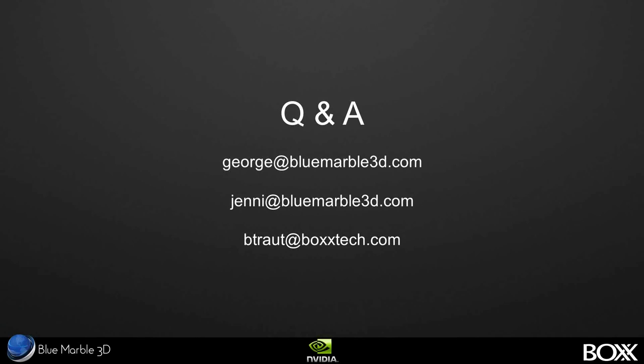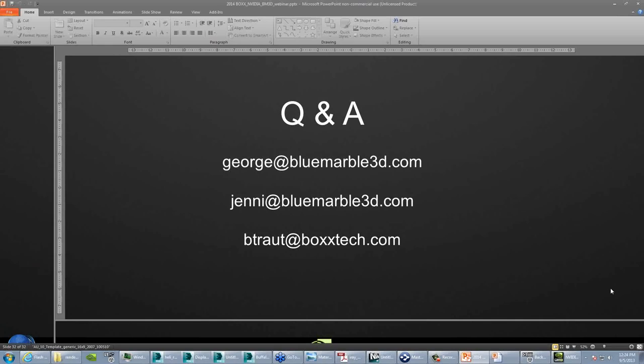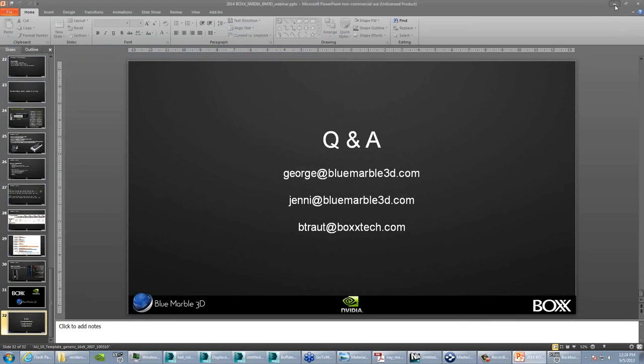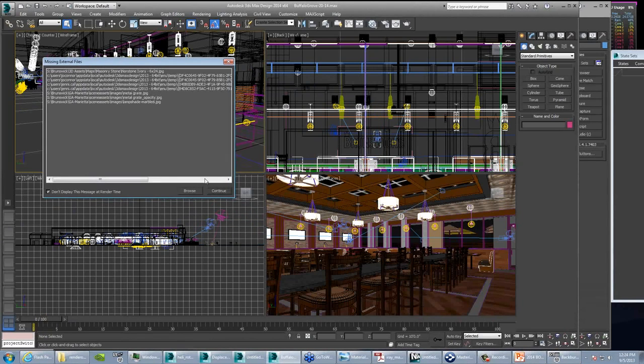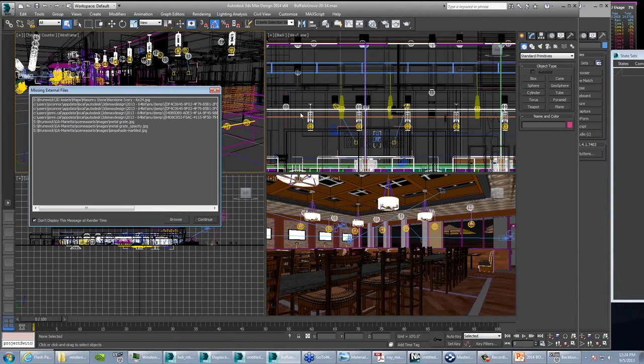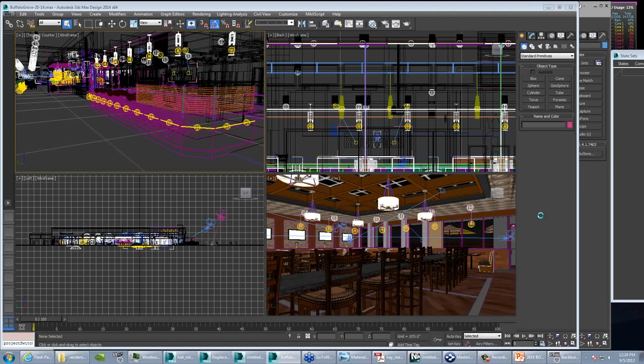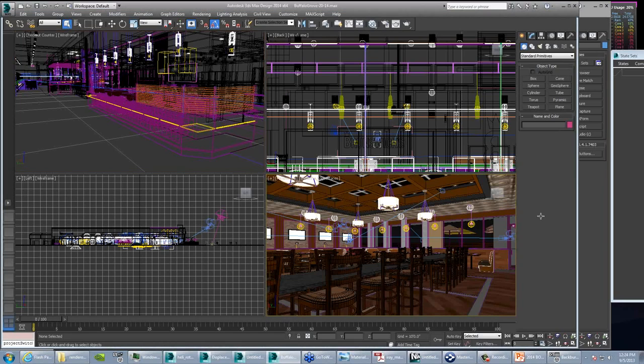Is there a difference in performance using material glossy settings, i.e. less glossy, more glossy, means fast or slow? So the question was whether adding glossiness to a surface impacts the performance of the rendering, and it certainly does with Mental Ray. A big focus of my book was optimizing materials, lighting, and settings to try to improve performance and speed. With Iray, we don't really worry about it, so we make the material look the way that it needs to, and go from there.